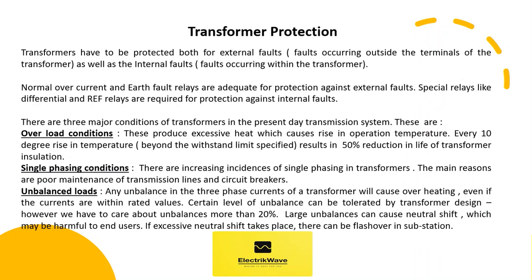Transformers have to be protected, both for external faults occurring outside the terminals of the transformer, as well as the internal faults occurring within the transformer. Normal overcurrent and earth fault relays are adequate for protection against external faults. Special relays like differential and REF relays are required for protection against internal faults.